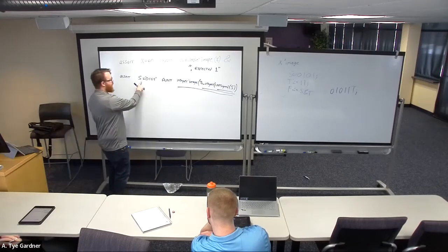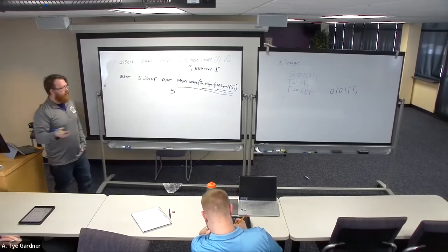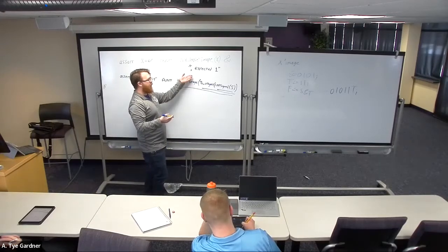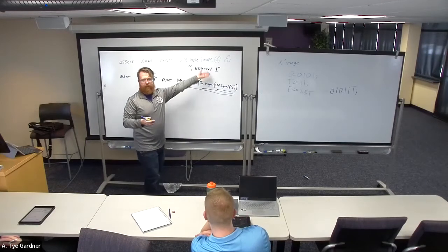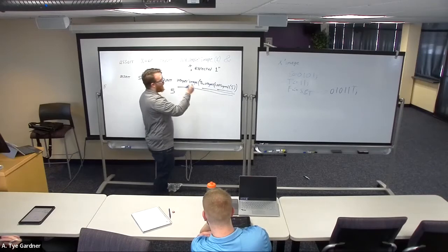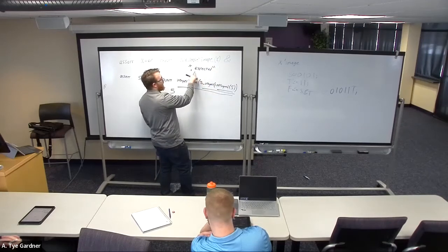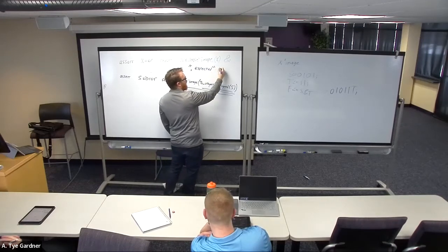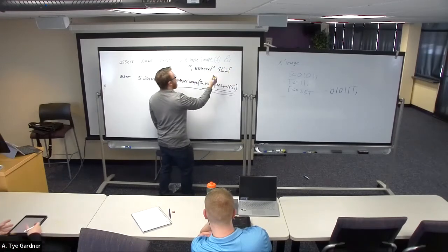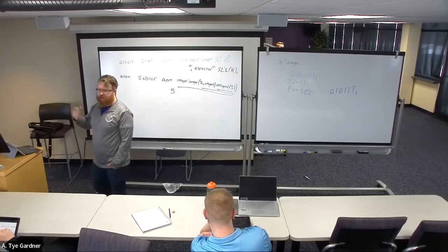So this report, if it's not this, it will say 5. I can then combine that with this idea and concatenate this and say something like "and expected" some value. And I can take it even further. I could do the same kind of thing: standard logic image and expected, and I could add this also, standard logic image of, I'm going to use R for the reference, whatever I knew it was supposed to be. So that way it's variable as well.